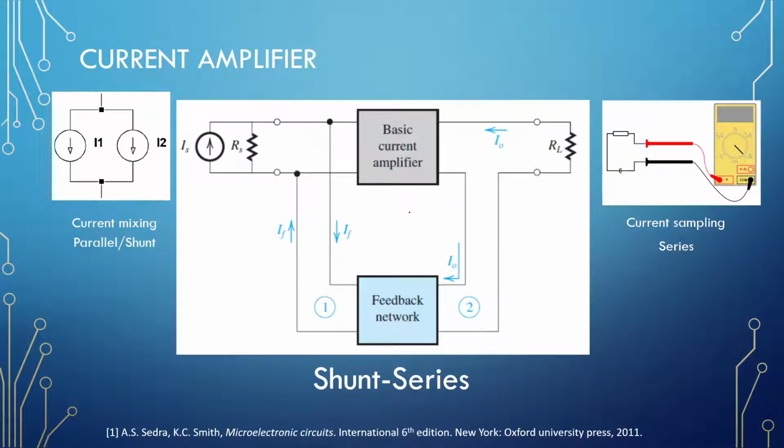Right, so getting to the series shunt part, currents are best measured in series if you use a multimeter. So our measurement in our feedback loop will always happen in series, so there will be impedance in here and the impedance inside of the amplifier, and also all the impedances will be summed when we're looking for the output impedance, and at the feedback side here everything is in parallel.